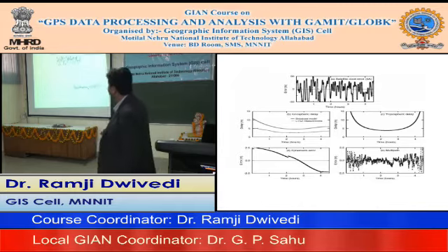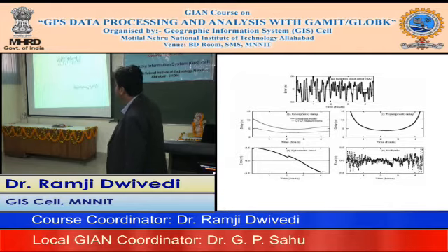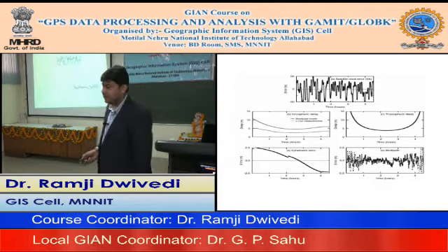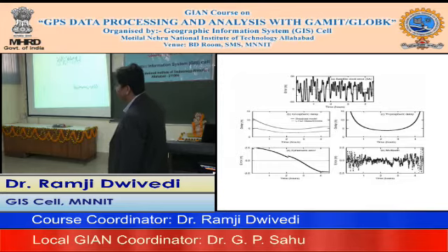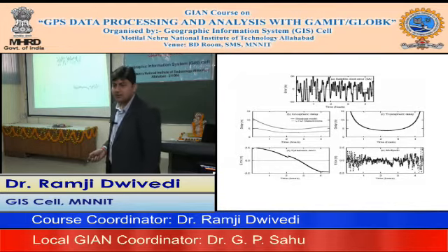The reference is not coming up; it's by Professor Per Enge from Stanford University. You could relate this figure one by one. This is the satellite clock error because of selective availability. You could see the deviations which are there for quite a few hours. These deviations could be limited if you don't have selective availability. You could also relate with the other figures. I'll take two to three minutes. You could see what the error sources are if you have these kinds of figures before you.